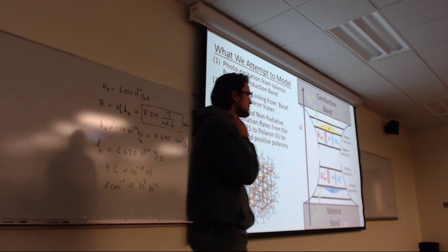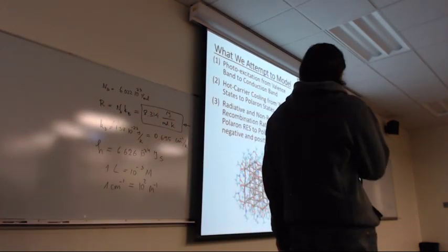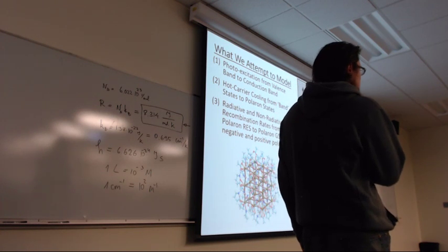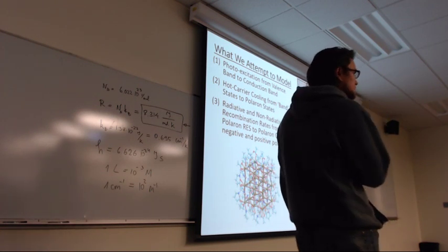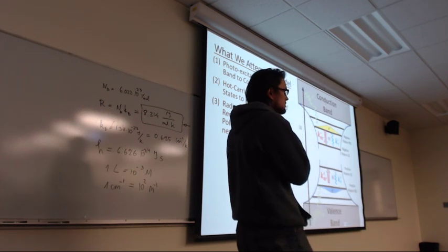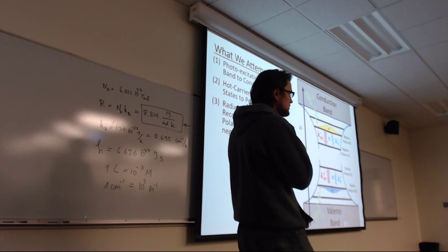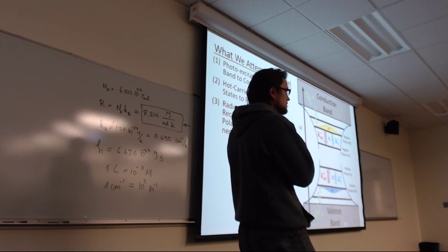So kind of related to the questions and discussion which we had before. Your picture is really considering an independent free electron hole pair. That is a very valid picture in bulk conductive materials, because your electron and holes are really not bound. But as soon as you bring confinement, your electron and hole cannot be far away anymore, and you really force them to interact with Coulomb interaction. You enforce the Coulomb interaction and excitonic effects due to the confinement. But you neglect this effect despite your confinement.